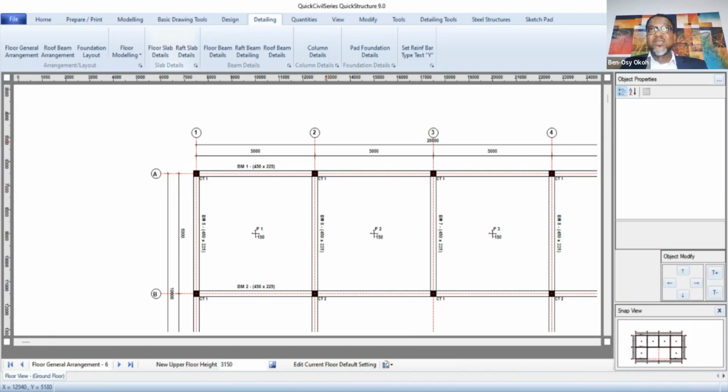If you add a column, break it into two, that column is not going to cause any obstruction. Now it's a choice for you. Do I have a beam of 8 meters? And if you have a beam of 8 meters, I bet you there is no way you will have reinforcement that is less than probably around 8 or 10 Y20, depending on the load it is carrying.